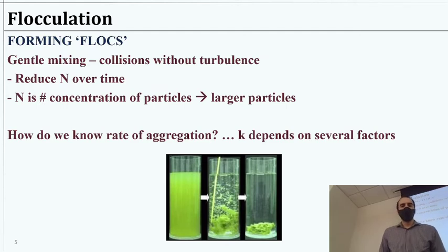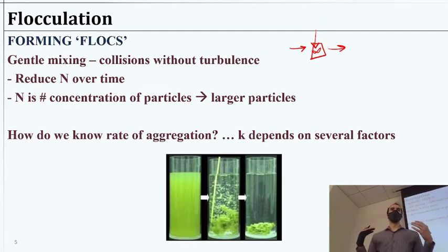For flocculation, the process is that after we destabilize, so we've added some coagulant, typically that's going to be the coagulation dosing, which I mentioned last time, a small box. It's very well mixed, water's coming in, water's going out, and we're just injecting the coagulant and dosing it that way. The coagulation chamber's only purpose is to add the chemical, mix them together, and then send it along. So coagulation is very simple. It's a very small reactor, very high mixing rate. That's basically all it is.